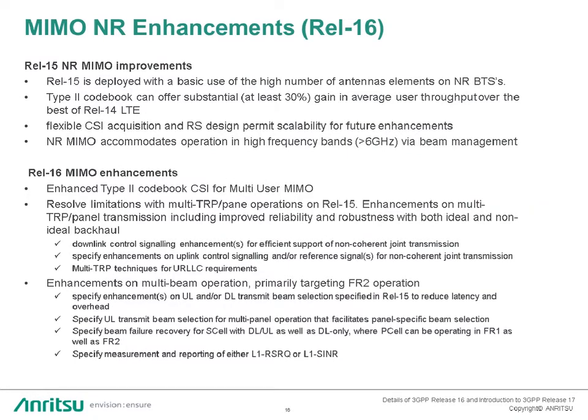Also, beam failure recovery for SCell with downlink and uplink as well as downlink only. Then there was more possibility to specify measurement and reporting. It could be based on either L1 RSRQ or L1 SINR.